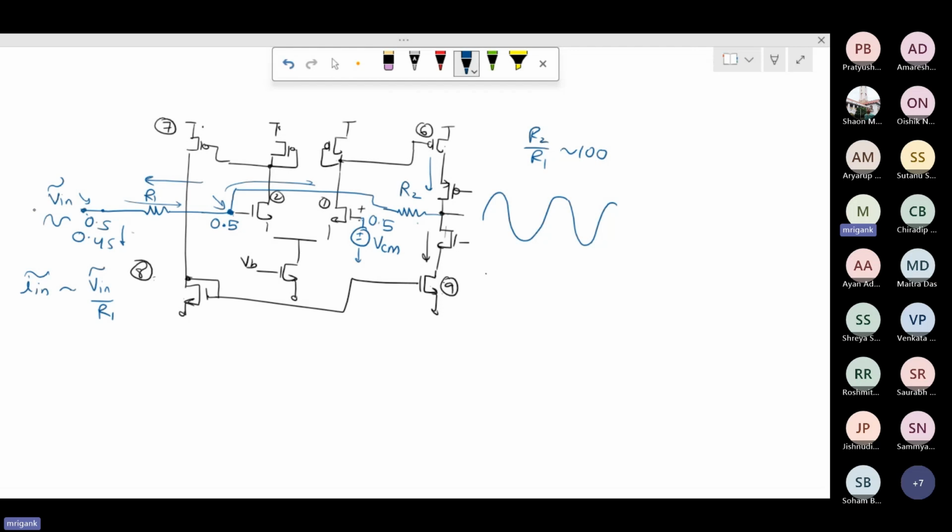So in this case, it is good to have a well-matched DC so that the DC conditions here and here are perfectly equal. They are well matched. But again, because of variations in the circuit, it may not always be possible, because you have seen that small variations in the circuit may lead to a difference between these two values. You may have a significantly different value over here. So right now what we got is an extreme, but at least a few millivolt difference you will get because of finite gain, because your gain is A0 upon 1 plus A0 beta, and it is only approximately equal to 1 upon beta. But the exact value is this.